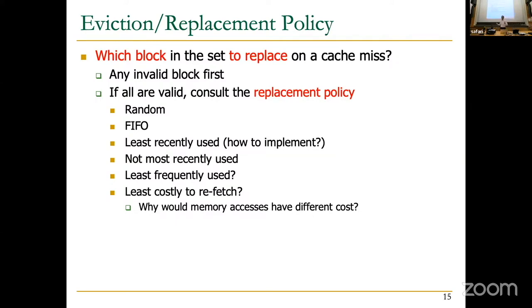Now, it becomes hairy in this case because you're not looking at just, right now, what am I going to access next? That's one dimension. Now we're also looking at how costly is it for me to bring the data into the cache. And this should factor into the decisions, as I will show you later in this lecture also with a simple and beautiful example, hopefully. This should factor into the decisions because, as we discussed, it's not just about the hit rate of the cache, it's also about the latency. So when you're managing the cache, you need to take that into account. And we'll put energy into it also later on. So it's a complex management decision. And we're just talking about a single cache. And then we're going to talk about the hierarchy soon.